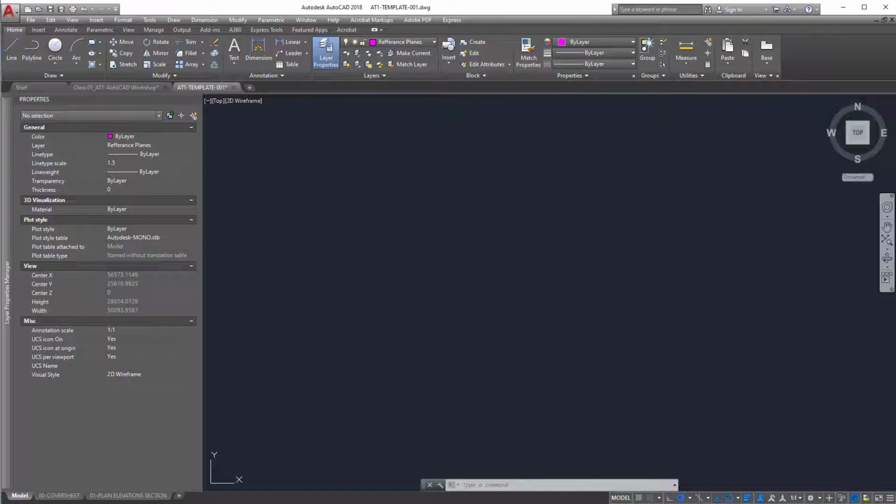So to begin, I'm going to draw a line. So L for line, enter, and then I'm going to type into the keyboard 0, 0, 0. And you can see that in the command bar at the bottom. Specify your first point, and the first point is at 0, 0, 0. So in other words, it is smack bang at the beginning of this drawing or the middle of this drawing, or what is known as the origin of this drawing.